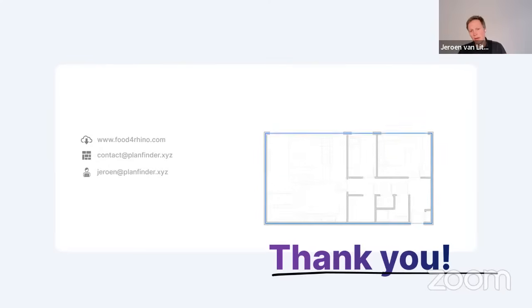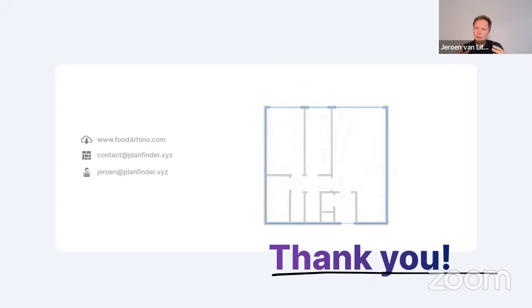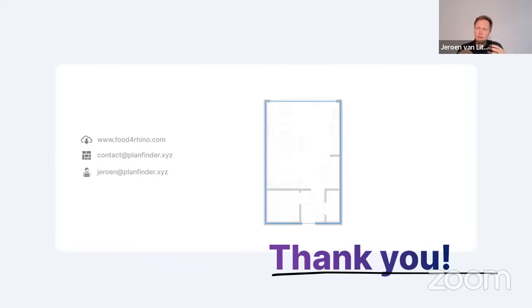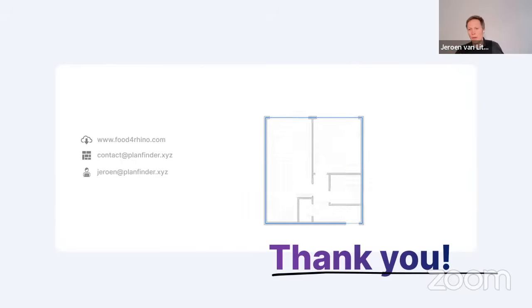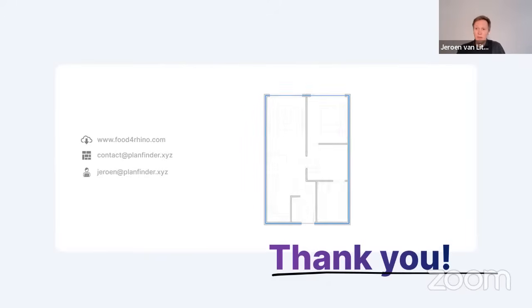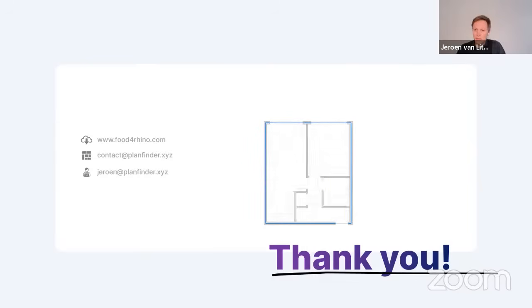In the Rhino version, you can get the internal areas of the rooms. And in the Grasshopper version, you can get the internal room curves. So you can build your own script to count everything. That's not something we built into the Grasshopper plugin, but because you have all this geometry as output, you can use it later in some sort of analysis for sure.